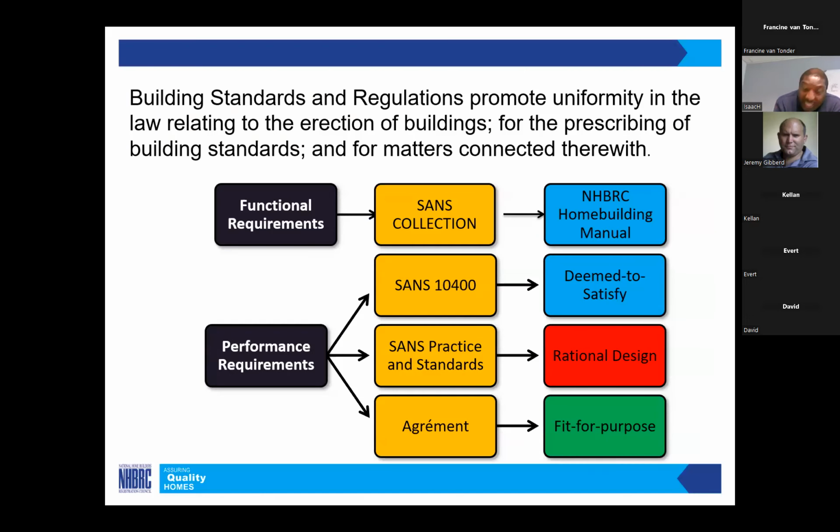Secondly, look at the functionality and the performance. Today, we're having different structures. There's no necessary need for a mass thick building. You can do a very thin structure which can be functional and perform correctly if you do your rational design, and you make sure that certain materials have been tested to perform certain functionalities in terms of fireproofing, water tightness, and structural stability. Or you can just go into the Agrément website and look into the systems that have been approved for building walling systems.